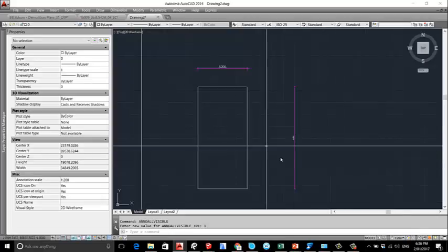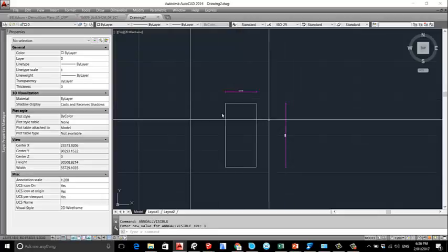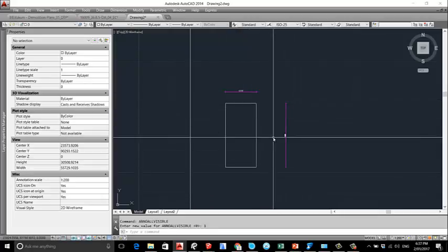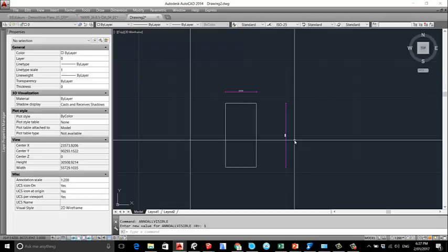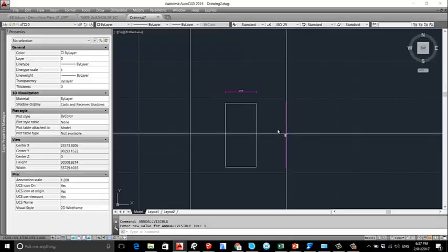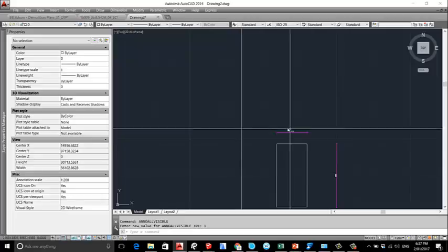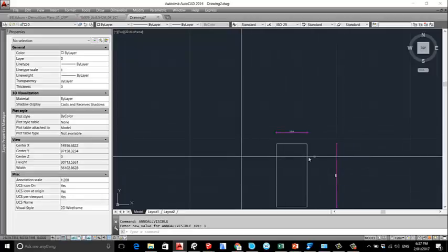And now you will ask, why do we need annotative scales? Because very often we show the same thing in different scales. Like for example, we print the site plan and then we print the boundary line in the site plan and in the ground floor, and the site plan might be 1 is to 200 or 1 is to 500, and we don't want that scale to be huge or unreadable. So actually this will vary automatically depending on the scale.